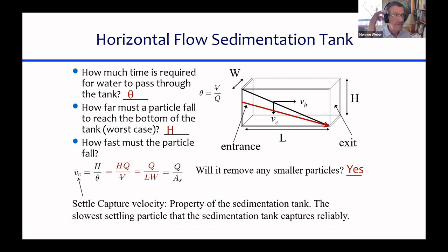And so every 6 months, when students are on break, they take down half of the sedimentation tank. They go in there with fire hoses and they blast it out, and they have a drain that it can go down, and it goes out to some lagoons. And it gets deep. I don't remember how deep it gets, but I think it may get like 8 or 9 feet deep of sludge, a lot of sludge.